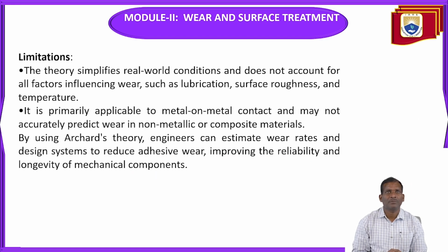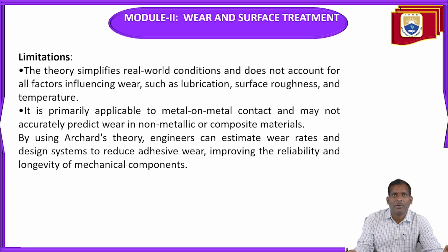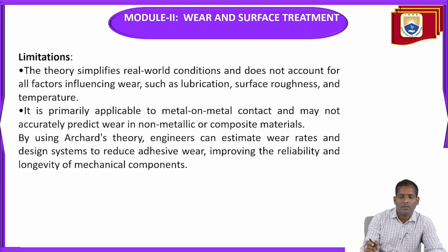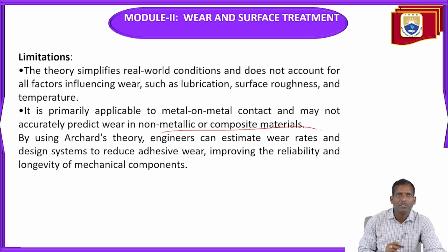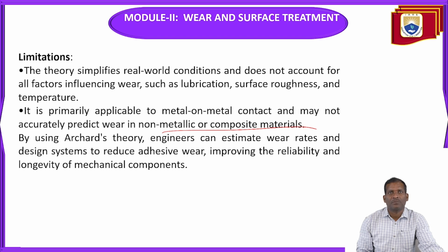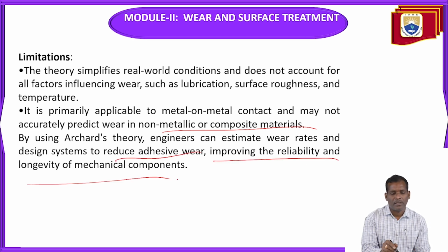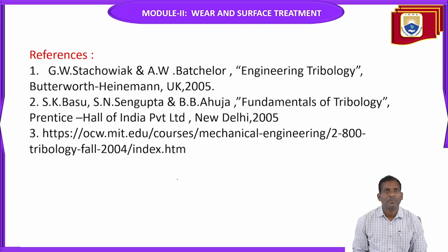There are limitations, such as lubrication, surface roughness and temperature. These are the real world conditions. It is primarily applicable to metal on metal contact and may not accurately predict wear in non-metallic or composite materials. By using this theory, engineers can estimate wear rates and design systems to reduce adhesive wear, improving the reliability and longevity of mechanical components.